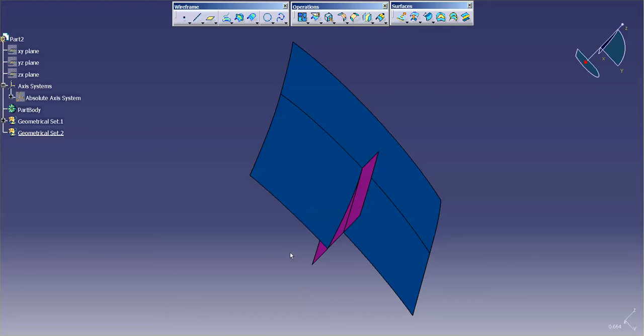Now, I do not like to create a cutback and just simply a transition surface or an S surface. You can do that, but in a lot of cases it's better to actually build all the way up and in through the transition with a couple of surfaces. You'll get potentially a better result, and you'll have something that you can actually change the way the highlights flow depending upon how you build.